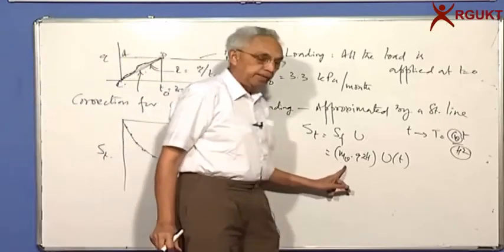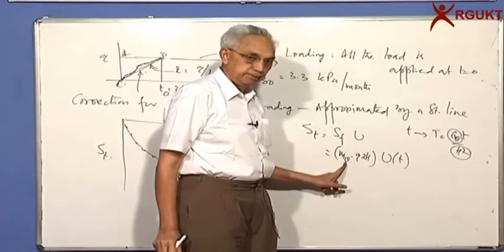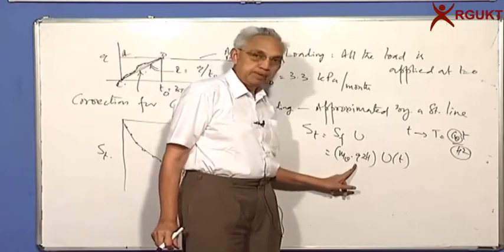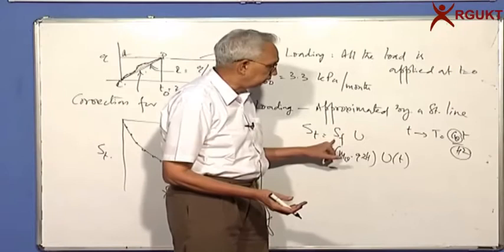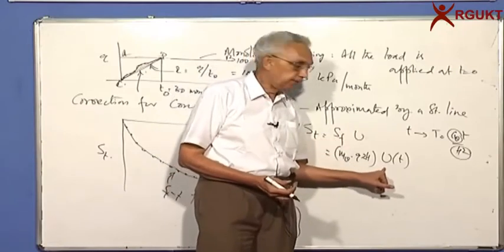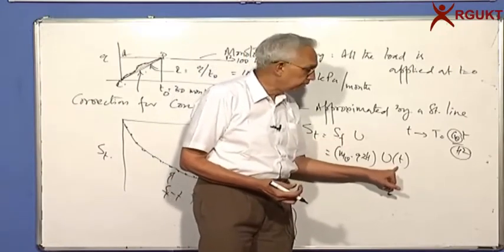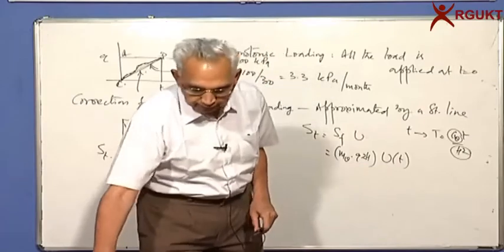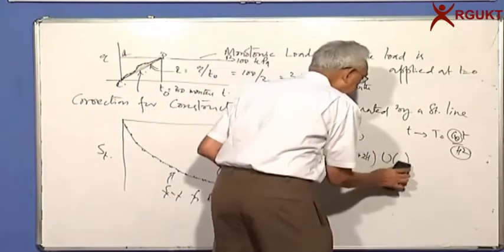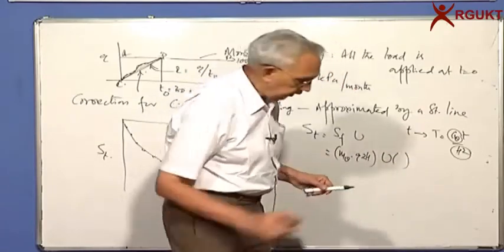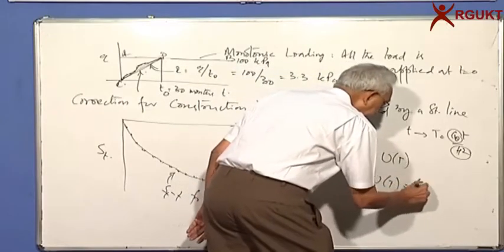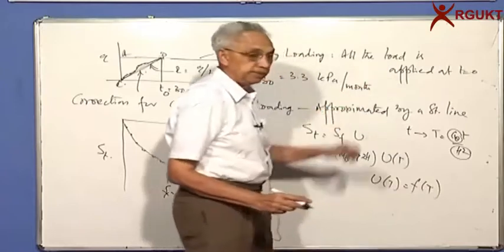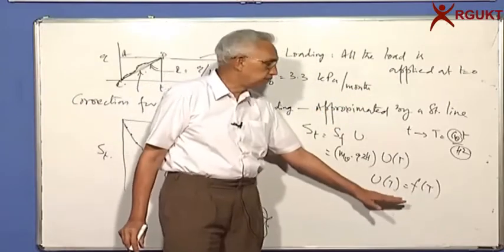We know the property of the soil, the compressibility in terms of coefficient of volume change, the applied stress, and the thickness of the layer. That gives me the final settlement into degree of consolidation as a function of time t, or you can even put it as a function of time factor T. You have derived the equation, so you know U_t as a function of time factor T. I have given the expression just now, so you know how to estimate that.